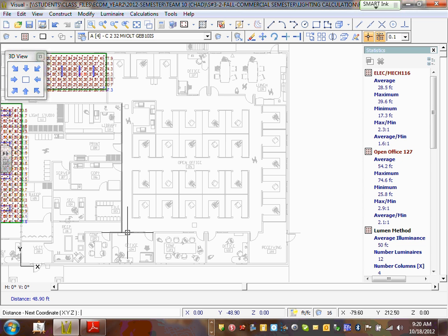So if you go make a box, 62 by 49, drop it here, right? Before you drop it somewhere here, and then bring the fixture here. Delete the box, leave just the fixtures, and then you can make another box here, do the same thing for this area, delete the box with the fixtures, and just put in little box by little box. Then delete the boxes, remember, keep the calculation, and then redraw the real location and run your calculation. Make sense? No?